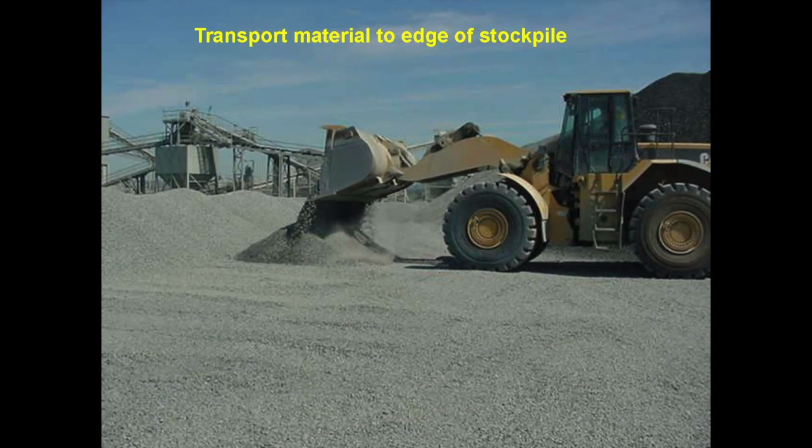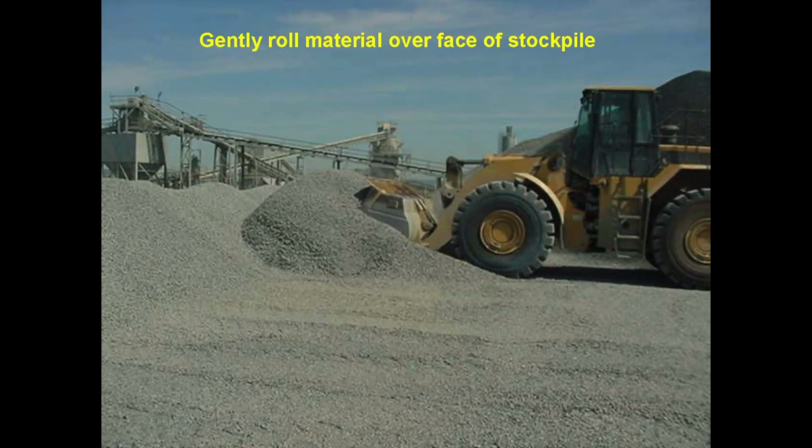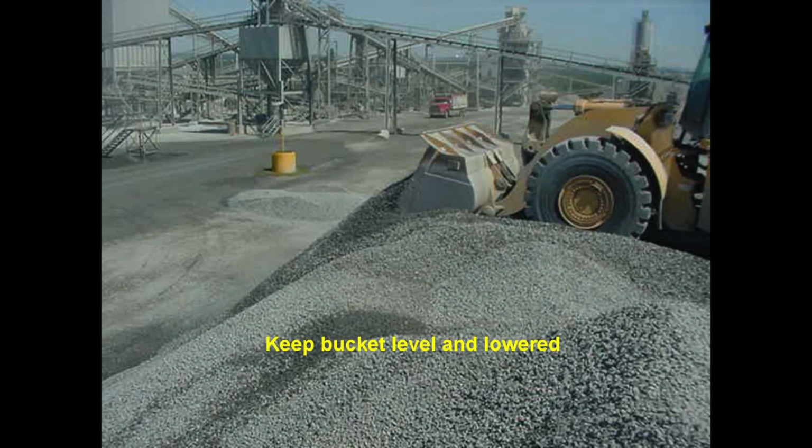So I'm building a mini pile now. I've taken the segregation that we get from having a conical pile, and I'm taking that out. I'm remixing it because I've got to move it from underneath the stacker anyway. So, knowing that it's going to segregate in the stockpile, I'm going to put it back together again. See how he's working the face there? And then push it over the side. And again, not throw it over the side, but push it over the side. Because he could build that mini pile and then pick it up and throw it over the side, and he'd be back at square one again, right?